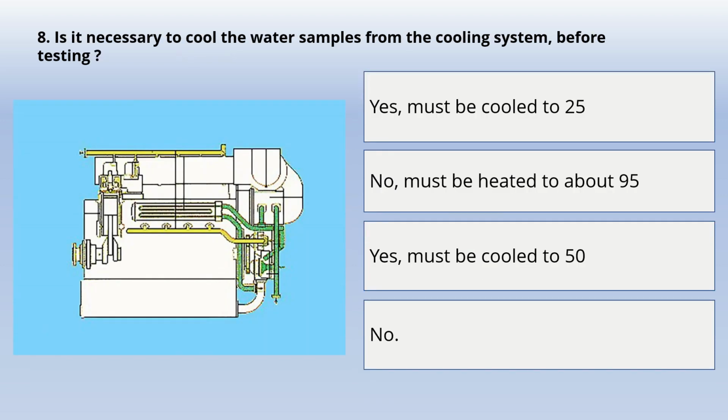Our next question is, is it necessary to cool the water samples from the cooling system before testing? Yes, must be cooled to 25 degrees Celsius. No, must be heated to about 95 degrees Celsius. Yes, must be cooled to 50 degrees Celsius. No. And the correct option for this question is yes, must be cooled to 25 degrees Celsius.